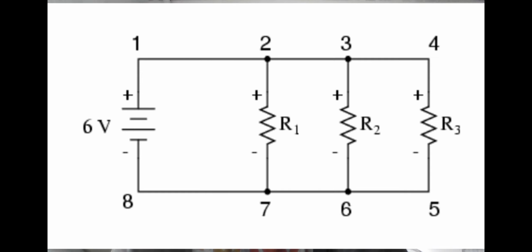If we look at a parallel circuit and diagram out all the voltages in it, starting from the negative end and ending at the positive end, as you would normally do when you analyze a circuit, we see at the first resistor, it is exactly negative 6 volts. At the source, it is exactly positive 6 volts. And for all of the wires in between the resistors and not on the resistors themselves, it is exactly 0 volts, as we are making the assumption that all of the connections between the resistors have no resistance.